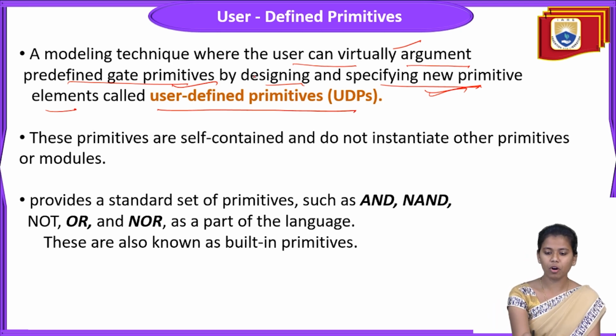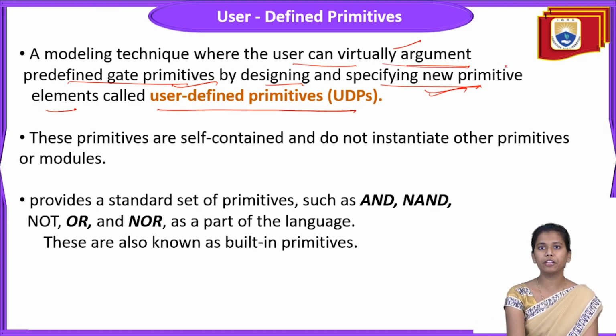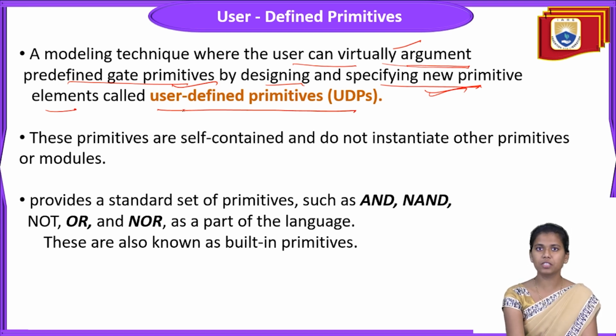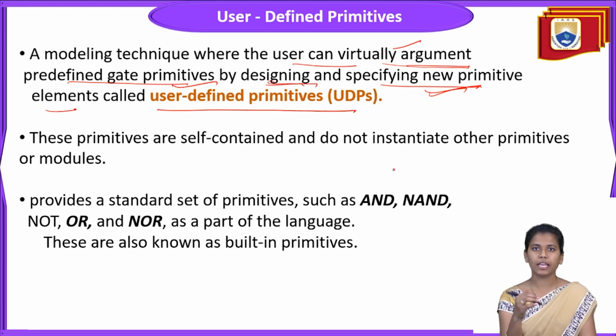So it is a modeling technique where the user can virtually augment predefined gate primitives by designing and specifying new primitive elements. Such elements are nothing but user-defined primitives, UDPs.